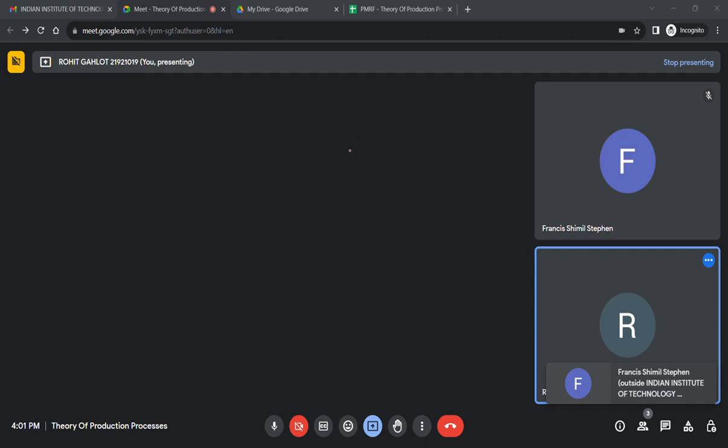So as it is given, 20% higher than this. Generally, as I just discussed, for 20% higher we do this by the modulus of the riser being equal to 1.2 times the modulus of the casting, right? So you just need to calculate the modulus of the riser in terms of dia.